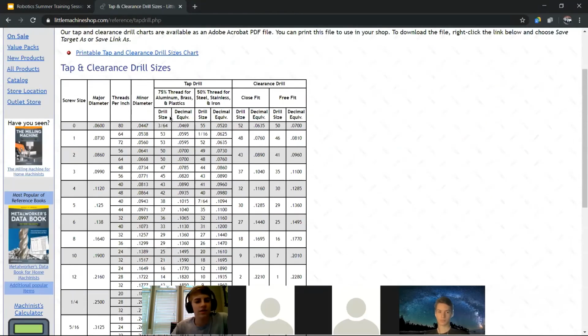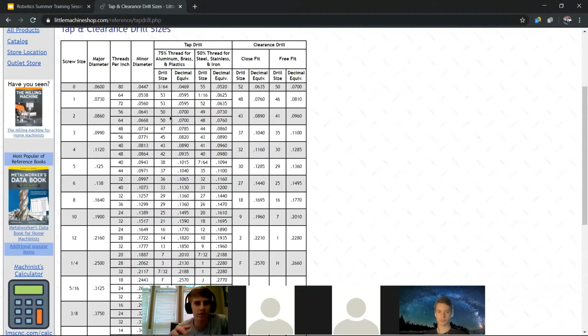So basically, a hole has two things that describe it. The first one is kind of like a reading of what the bolt is. So you can have like 5/8 or 1/4. This is the screw size right here. The second one is how many threads there are in an inch. So in FRC, you've probably heard when we say we want an 8-32 bolt, that means it's a screw size of 8 and there's 32 threads per inch. So in this case, what we're going to be using is a quarter screw size with 20 threads per inch.